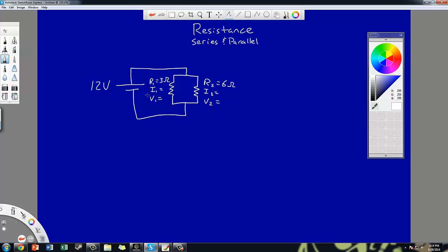In this case, I'm going to overcomplicate it just real quick as I explain what the normal pathway for solving these types of problems is. I'm going to do that because I know that V equals IR, but I have two different R values, so I have to consolidate. I'm going to call this parallel here because they are in parallel, and I'm going to redraw this with only one resistor,